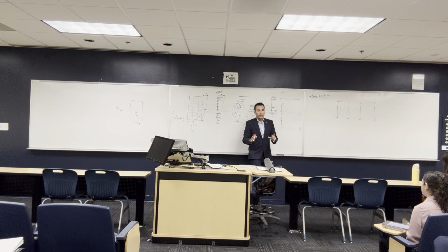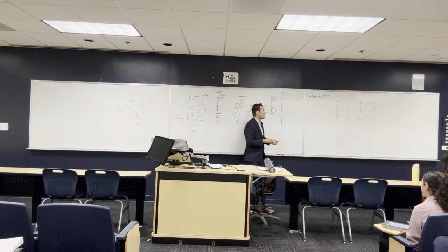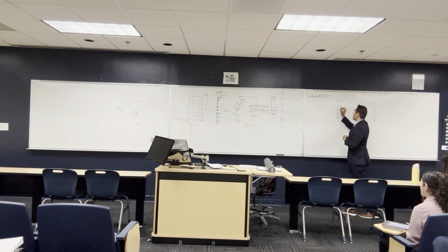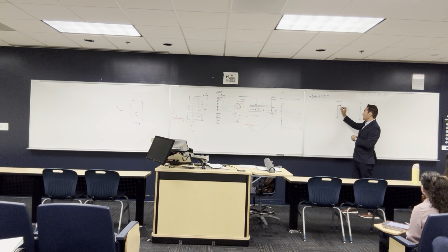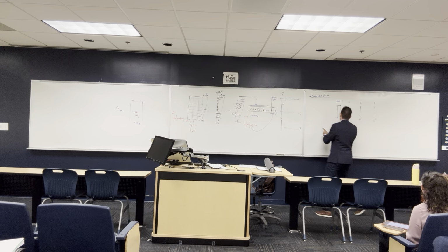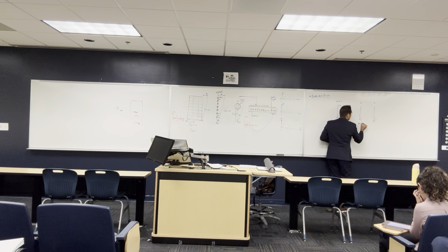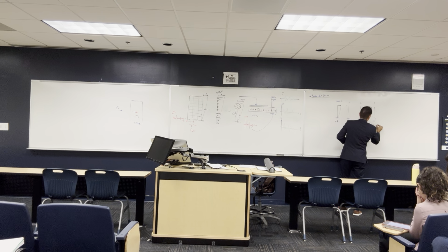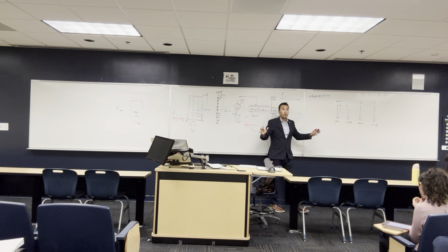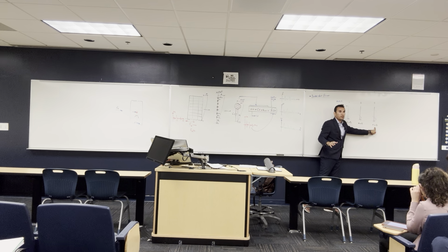And the mode shapes basically oscillate the mass, the same way that the mode shape is moving. Let's say this one is going to take the mass all the way here, but this one is going to take the mass the other way. The contribution of both of them, by the way, is not equal. Let's say this one is 90%, 0.9, this is 0.05, this is 0.03, and this is 0.02. That's the 100% of the movement. 90% is coming from this mode, but you cannot see these because they are very small.